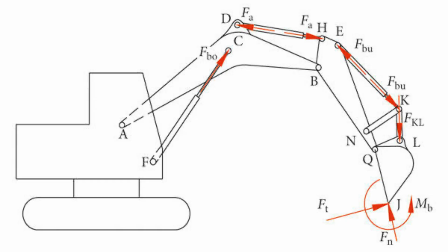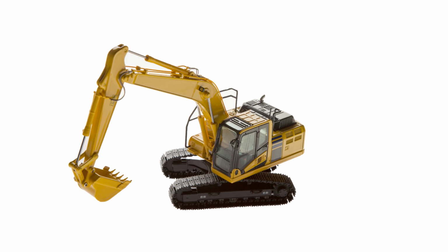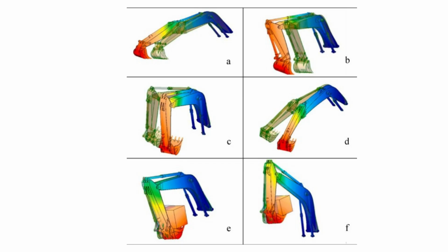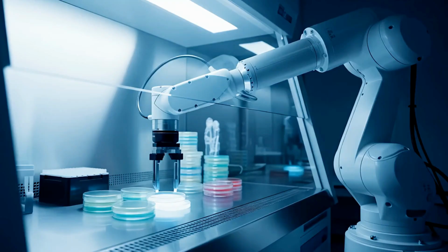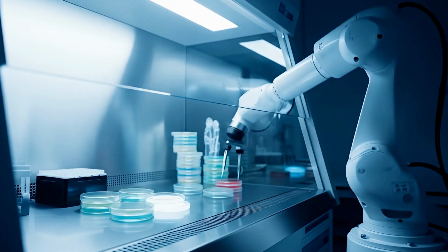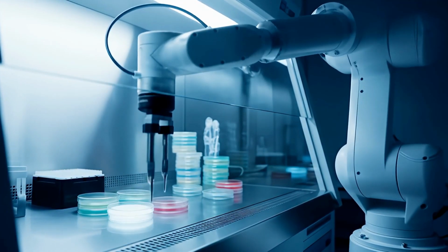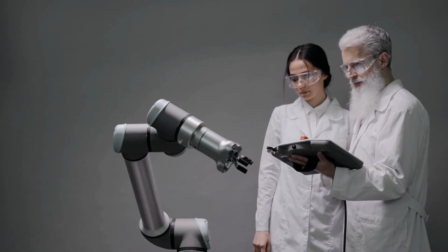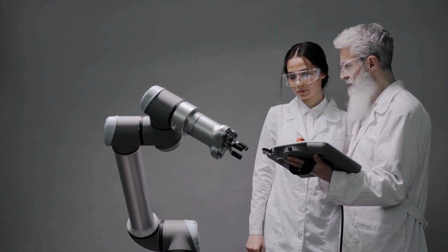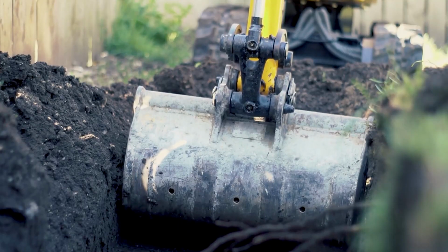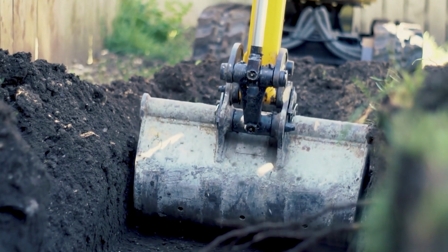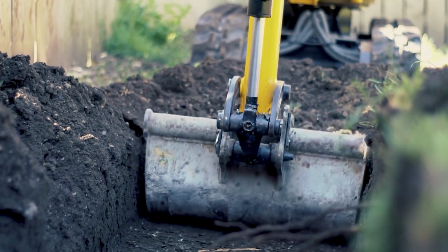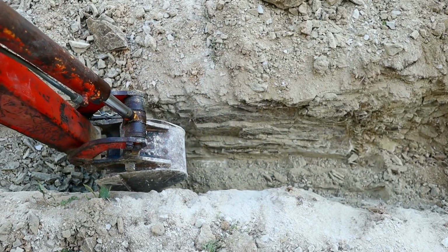Reverse kinematics is used in excavators mainly in special cases, such as research machines, autonomous digging prototypes, and simulation or offline planning. It is also common in robotic arms and electric machines, where actuators can precisely follow calculated joint angles. Even in these cases, reverse kinematics is usually applied only at a high planning level. The actual machine motion is still tracked using forward kinematics feedback, and reverse kinematics does not directly control hydraulic valves.